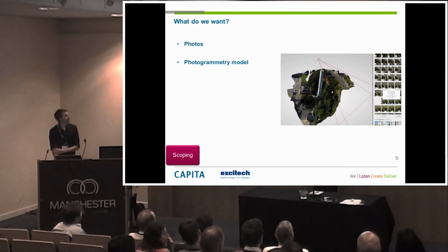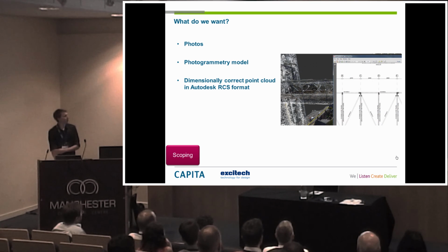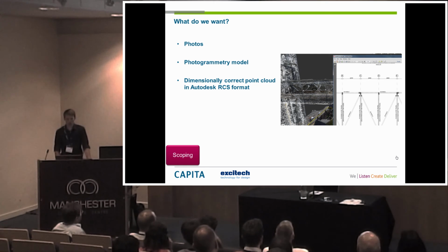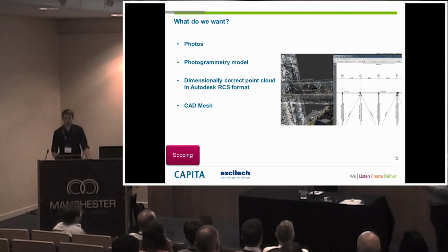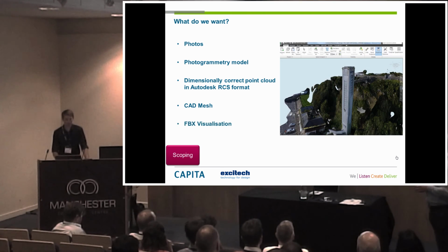So yeah, on this project, we worked out we wanted the photos, we wanted a photogrammetry model, a dimensionally correct model inside Recap, the Autodesk point cloud format, because we were going to use it inside Revit, a CAD mesh for a background reference, and also as a nice to have was an FBX visualization so we could do some visuals on the project.